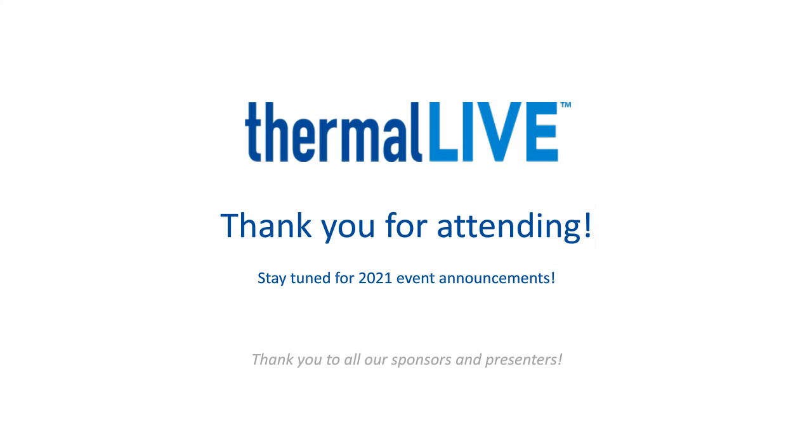Uncompressed metal foam can be produced with a porosity up to about 85%, which, if you think about it in terms of relative density, as I often like to do, from the point of view of the metal content, is about 15% relative density. Now that is just uncompressed foam, and as was noted in the presentation, you can change that dramatically by mechanically compressing the foam. So with compressed foam, you can go all the way down to about 50% porosity.